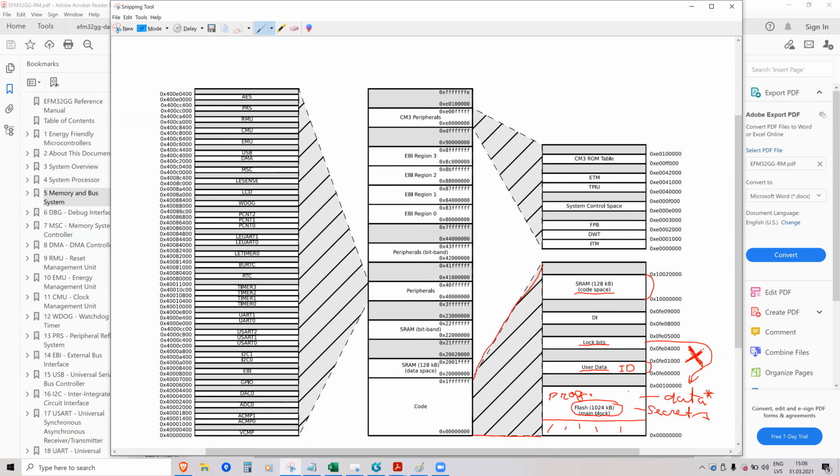And also you can write some functions which rewrite the flash, but this code that rewrites the flash has to be stored somewhere outside of the flash, because if you do the firmware upgrade and you override the function which performs the firmware upgrade, then your microcontroller will just stop working, or it will start to work in a weird manner because it overrides itself.